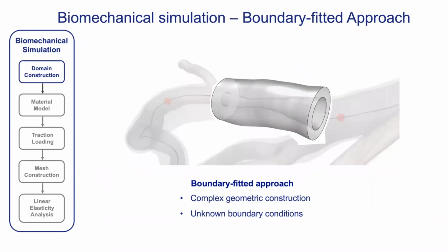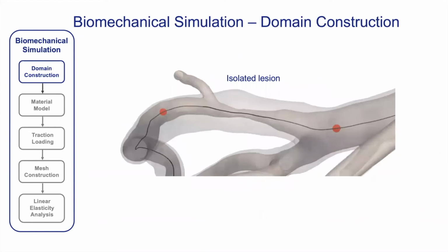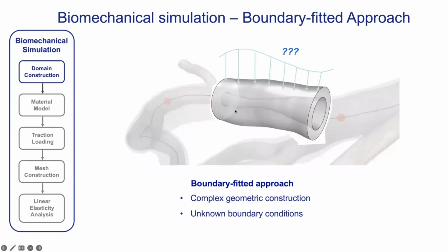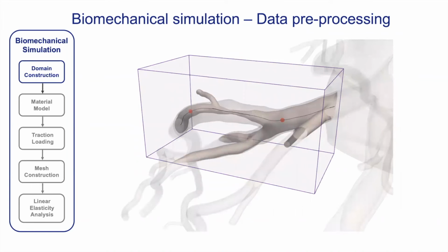And you might say, well, that region looks like a tube. Yeah, it does. But of course, you've got a bifurcation there as well over here. So could you model that as a tube? Well, you could, and you could mesh that any way you liked. But the problem is you don't know the boundary condition here. The heart is not hanging in space by a string. It's surrounded by tissue. It's encased. So all of that tissue is around there, and you don't know what the boundary condition is. So the only way to deal with that is to model it. So we put a bounding box around it and do an immersed type approach.